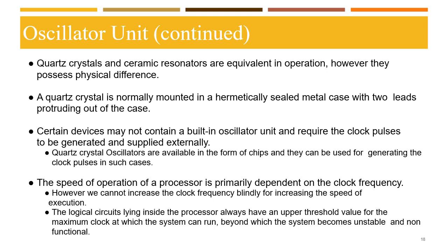We can't blindly keep increasing the clock frequency to increase the speed of execution, because the logic circuit inside the processor always has an upper threshold for the maximum clock at which the system can run. Beyond this, if you keep increasing it, the system becomes unstable and non-functional.